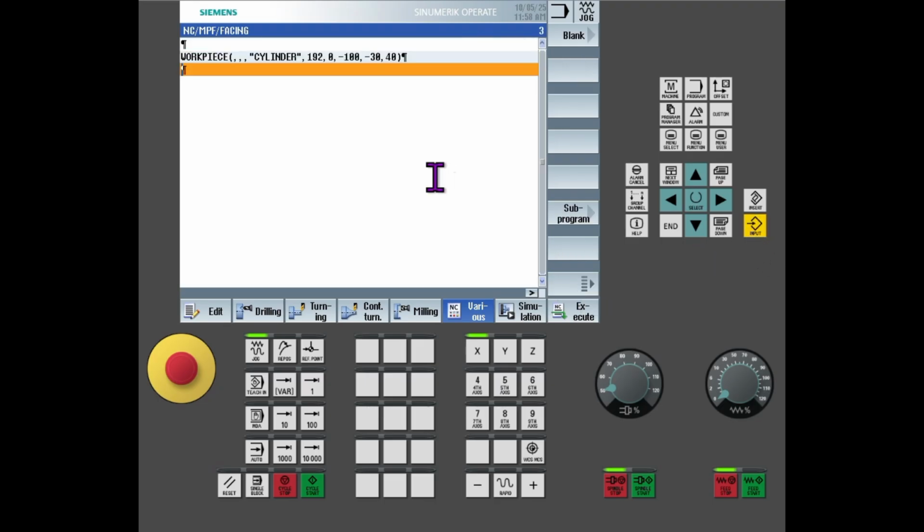After that, press input, then you write down the pre-operation commands. So in my pre-operation command, the first G code is G90, which activates the absolute mode. Then you write down G71, which activates the metric mode, meaning all the dimensions here will be in mm. Then you write down G95. G95 is your feed in mm per revolution. Then you write down G64. G64 is your continuous path mode, where the machine attempts to maintain a constant velocity across the block transitions.